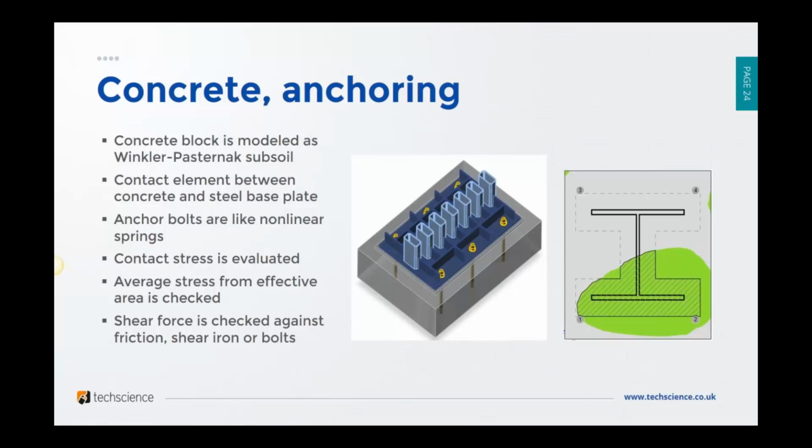In this model we calculate contact stress under the base plate, then we derive the effective area like in Eurocode and calculate the average stress for this effective area, which is checked for concrete ultimate capacity.